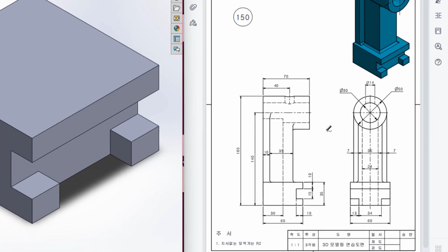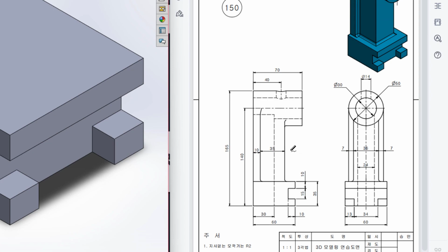So after that, we can see we have a rectangular shape like here. Okay, for drawing this rectangular shape, we can see it has a front view distance of 35 unit, and in the right view it has a distance of 36 unit. So in the top plane, I will draw a rectangle of 36 unit by 35 unit.